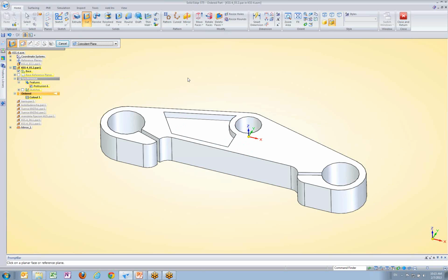All right, let's add a couple more features to get this design going. I'm going to hit create a round to round out some of these bottoms in here. A nice way to save time is to change your selection criteria. I'm going to grab a feature, and I'm going to put in a 2mm round, and that should grab any edge associated with that feature.